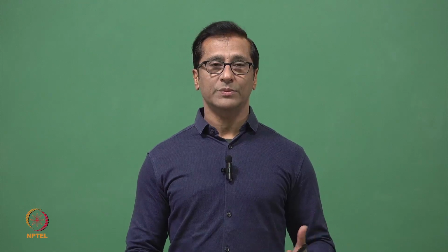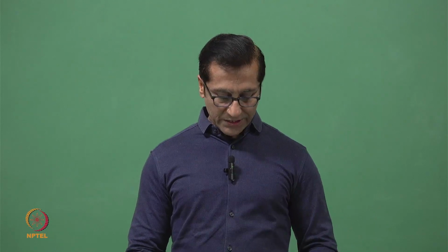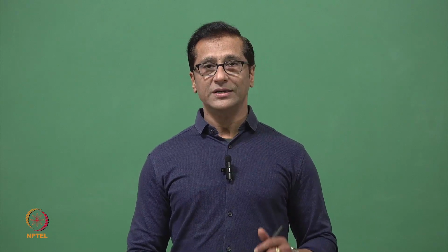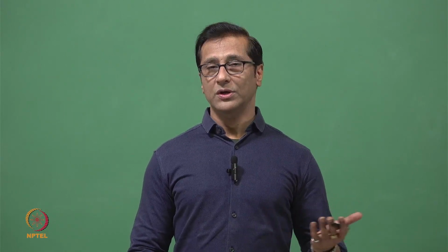Of course, a lot of research is being done, and based on length, perimeter and area, we can decide whether this is fatigue wear, adhesive wear or abrasive wear. That can be done, but it will be dealt with in lecture 18, not in this lecture. Here we are trying to give some fundamentals and some challenges that we need to solve using sophisticated, more mathematically oriented algorithms.